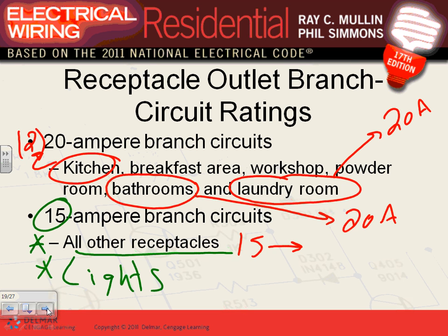Most of the time for lights, you end up with close to 10 or 11 lights. Receptacles, you can put up to 9. A lot of designers limit it to 6. We'll talk about these rules when we get to commercial. For residential, guys, on a 15 amp circuit, you can put up to 9 lights or receptacles. Nine lights or receptacles is a good number to put on a 15 amp circuit. Up to 9, you can.